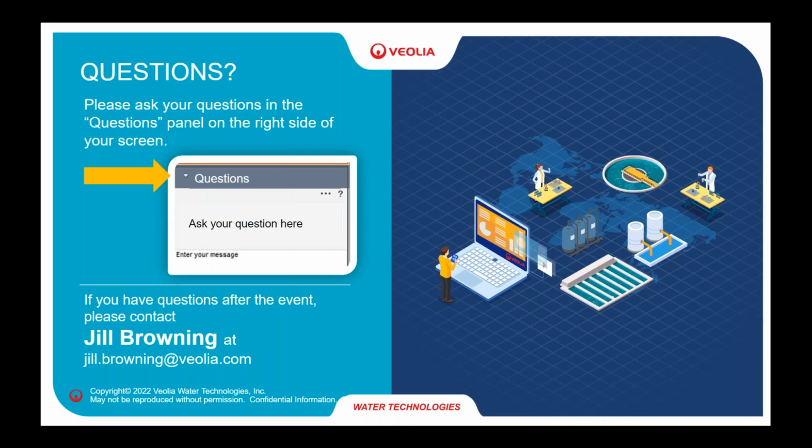Great, thanks. Another question that we've got here as well is talking about the retention time within the MBBR, and what exactly was that? Again, the conventional system has a retention time that depends on the concentration, probably I would say a day, depending also on temperatures. We found that in the application we tested, we're more at the scale of maybe 4 hours. Miriam, would I be completely off? Somewhere around that, yeah. It really depends on the concentration going in the system.